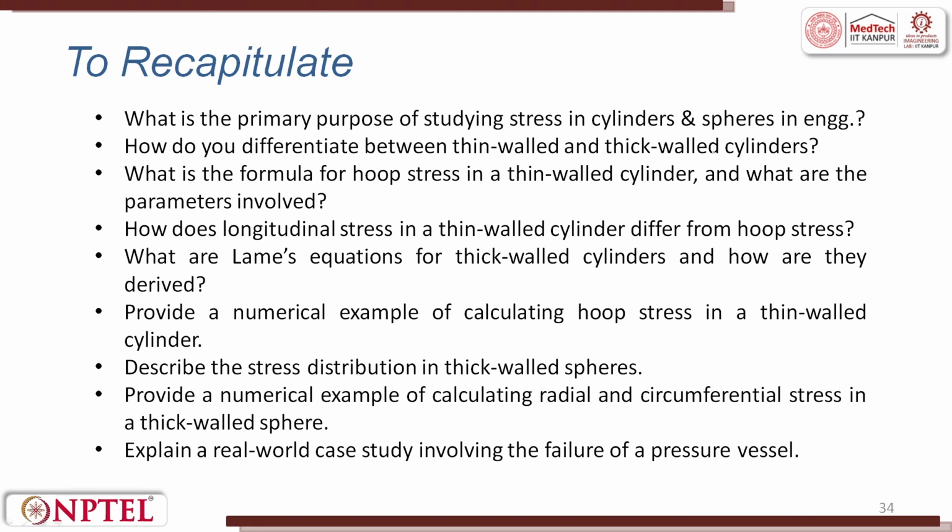We underwent a numerical study. Then we saw the stress distribution for a thick walled sphere. Then a numerical problem was solved. Finally, we saw a real case study wherein failure has happened in a pressure vessel. The importance of internal pressure getting developed, and wall thickness, are very important when we work on either cylinders or spheres.